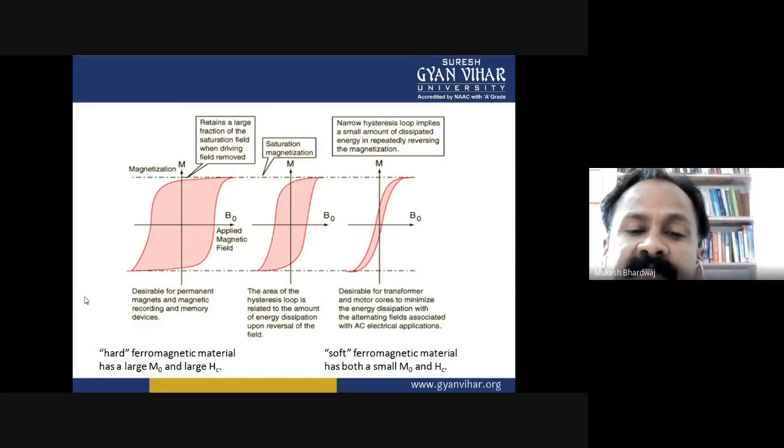Soft magnetic materials form the magnetic circuit in an electric machine. An ideal material for this purpose is one exhibiting the highest possible permeability and saturation flux density and the lowest possible core loss. Normally, the machine's performance specification dictates the material to be used for a given application. For small rating machines, it is normally the cost.